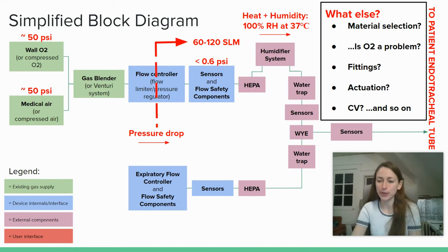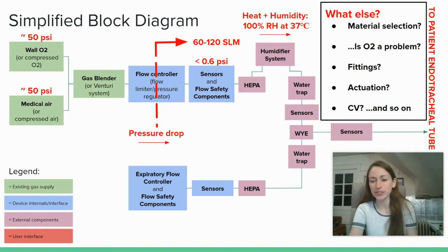You really need to think about material selection, especially because this is a biomedical device. You may want to avoid substances such as brass, which may be leaded to ease the casting process, and may also interact badly with high oxygen levels, especially if the doctors boost up the oxygen concentration to closer to 100%, which only happens in rare cases, but it's still worth thinking about.